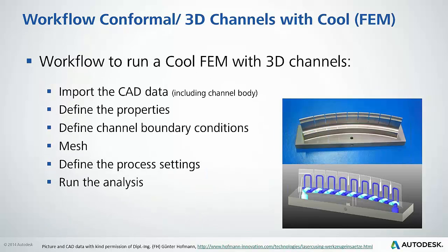So the workflow, this is kind of tongue-in-cheek. I'll try to step through it. Again, we don't have a lot of time today to go into a great amount of detail, but the really quick pass-through is we need to import CAD data, and that includes a channel body. So, as opposed to how we've approached a beam element, we can create that in Moldflow or leverage some 3D mold designs in CAD and lay out IGES lines, IGES center lines, right?